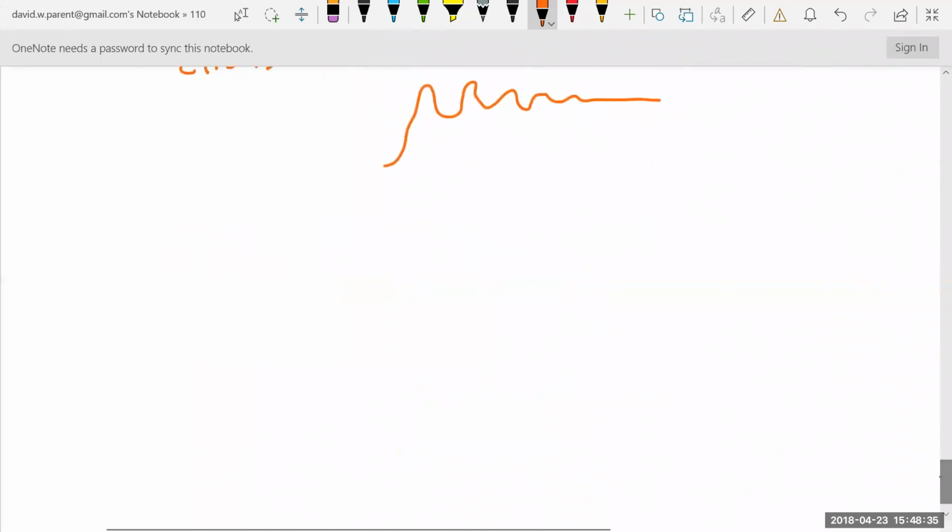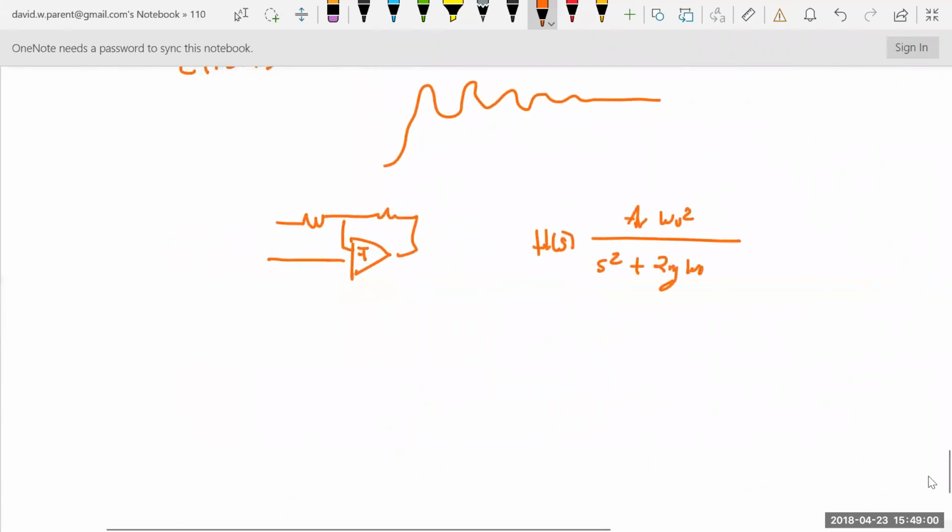But that whole thing with the op amps, where you can have just a simple non-inverting op amp, and you can have H(s), you have some DC gain, that way you can put this into a feedback network and make the real term such that it will oscillate.